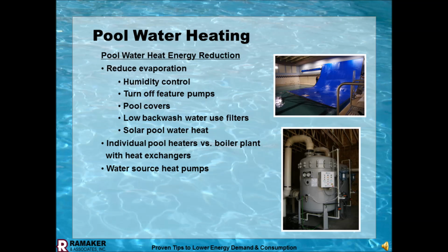Relative humidity in a water park where people find it most comfortable is between 40 and 60%. In the upper Midwest, we're able to just use the outside air and not do any dehumidification or humidification.